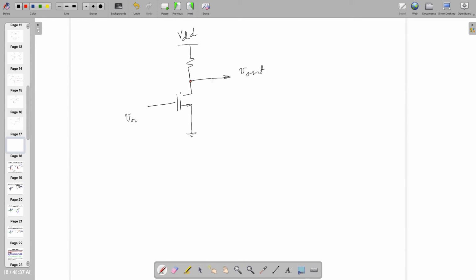So at this point, the output impedance, and from here, what is the source impedance? So this output impedance divided by the source impedance, times the current flowing through this one, which is ID, and the current flowing through IS. Both are the same, so it's gone, right? So this ratio is going to give me the small signal AC gain.